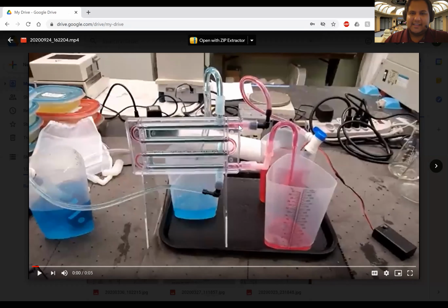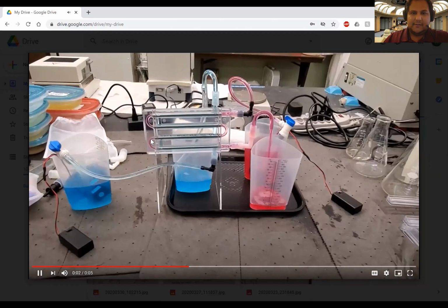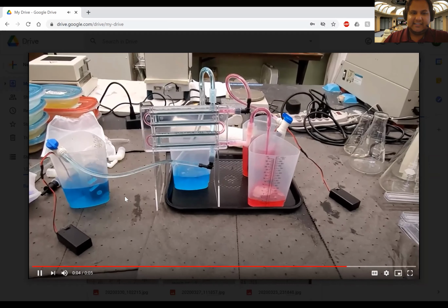The hot fluid enters the heat exchanger on the top, and it moves on the interior. So it's what we call the tube side of the heat exchanger before it essentially leaves out of the bottom of this heat exchanger. And to counter this, the blue fluid enters the bottom on the shell side, or outside of those tubes, and it moves up through the heat exchanger where it leaves out of the top of the exchanger. So when I hit play, it's a short video, you can see how these fluids are flowing through this heat exchanger.